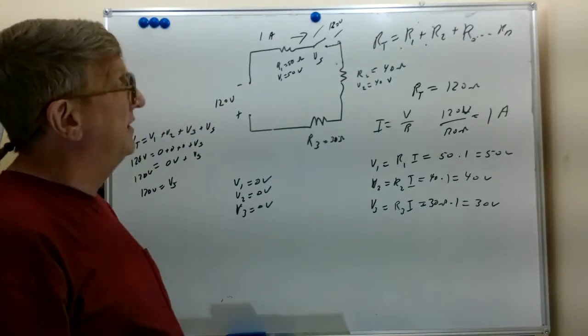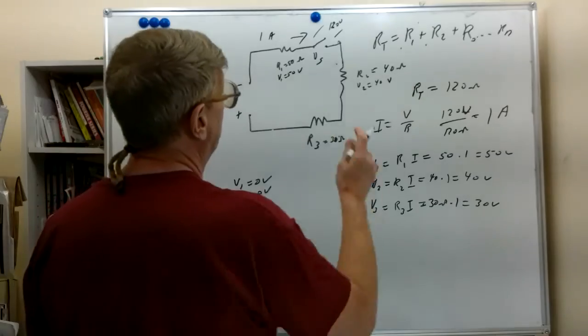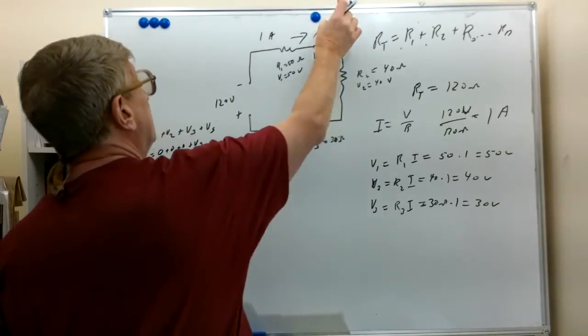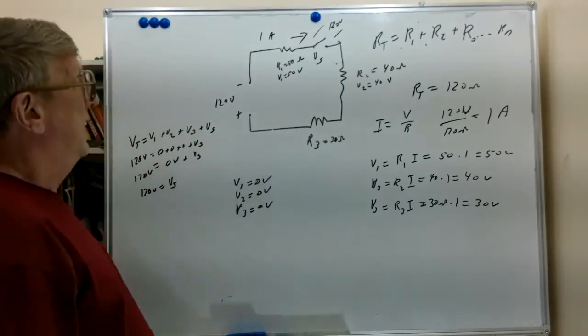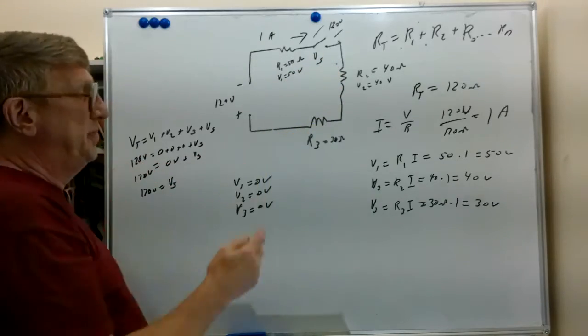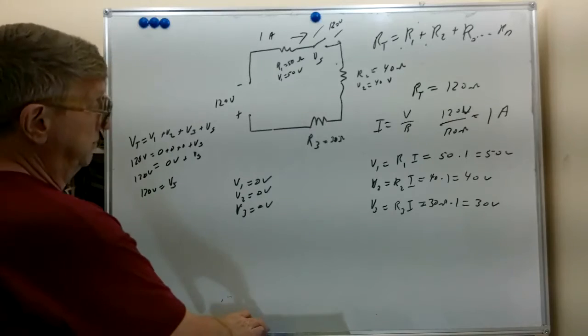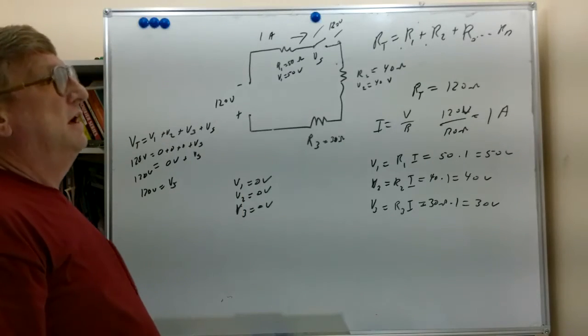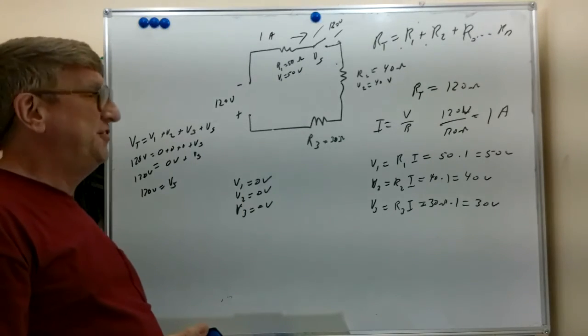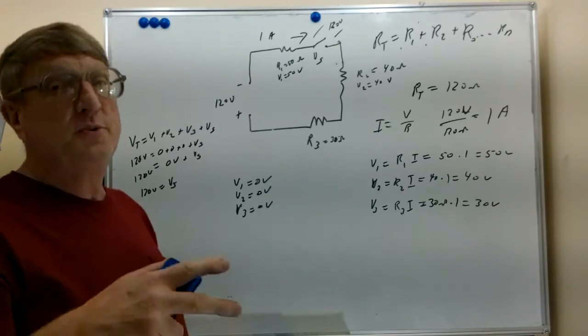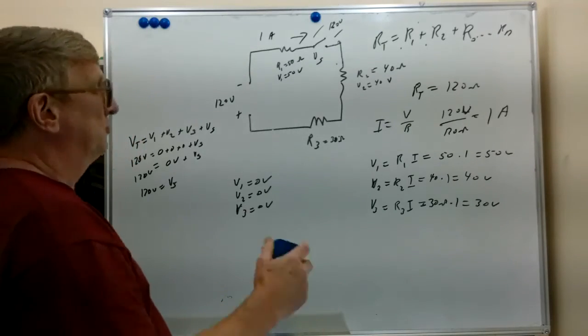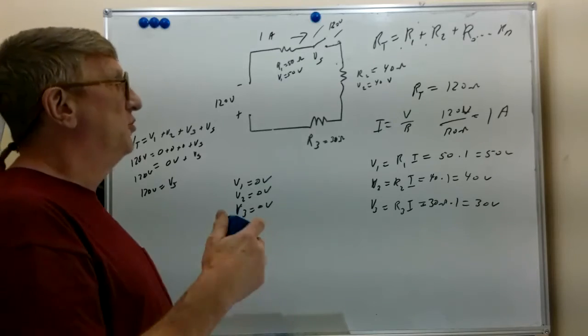We close the circuit. Now our resistance is essentially 0. No matter what the current is, we should see 0 volts. And our voltage drops appear again in the places where we expected them to be. So a good switch in operation closed, you put your voltmeter across it, you read 0 volts. A good switch, when it's open, you'll read the full voltage.